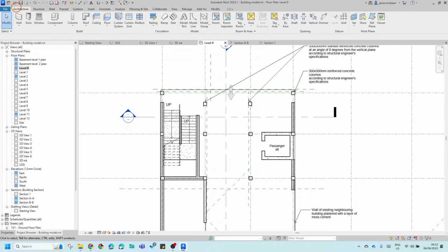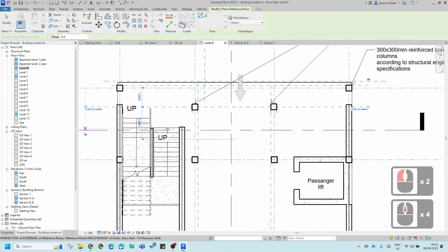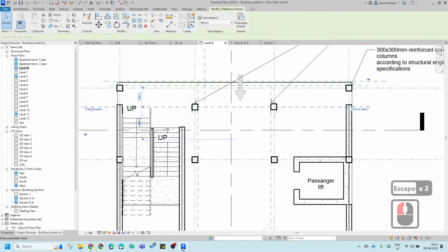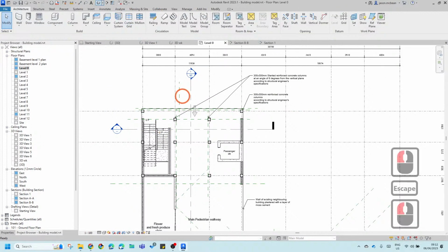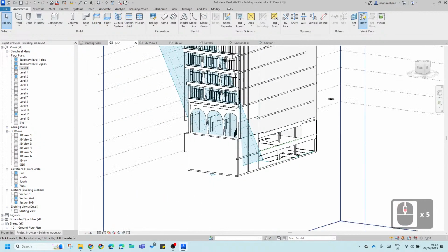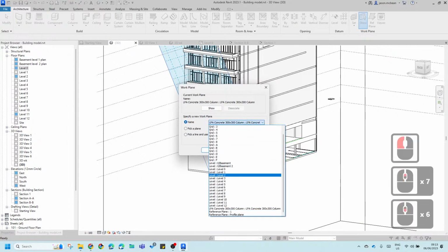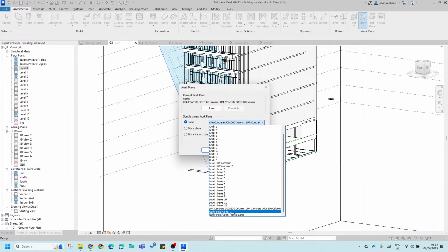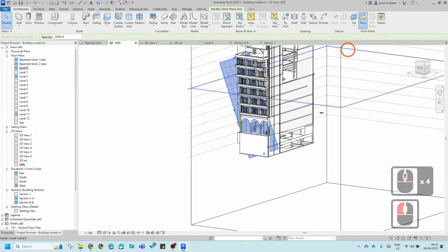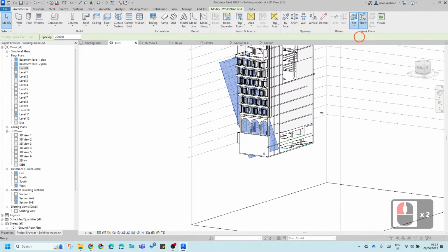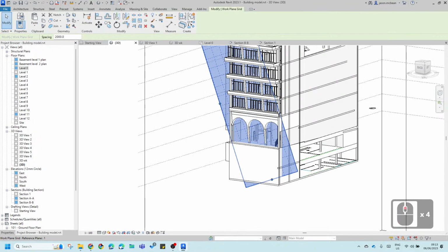You can also use architecture. You can use a reference plane anywhere. So reference plane is a construction line. When you give the reference plane a name, it becomes like a work plane. So if I go to 3D view, I'll just show you this in this 3D view, and I go and say set, you'll notice if you go to reference plane here, there's that one that I've named. Okay. Now if I say show, so let's just say architecture, just make sure it's set work plane, yep, and say show. Now it's working on that plane.